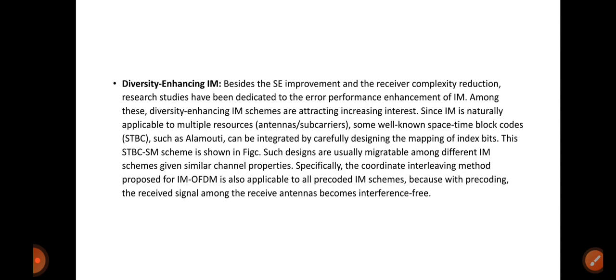Diversity enhancement IM. Besides SE improvements and receiver complexity reduction, research studies have been dedicated to the error performance enhancement of IM. Among these, diversity enhancement IM schemes are attracting increased interest since IM is naturally applicable to multiple resources. Some well-known space-time block codes such as Alamouti can be integrated by carefully designing the mapping of index bits.